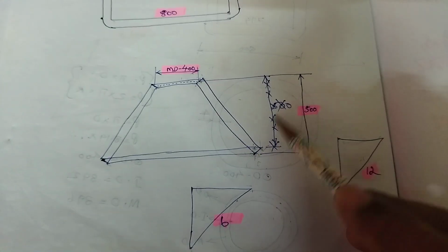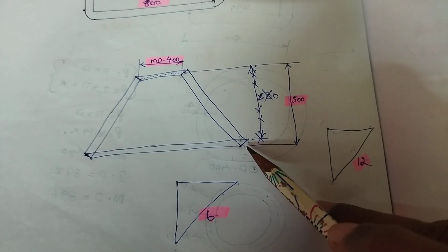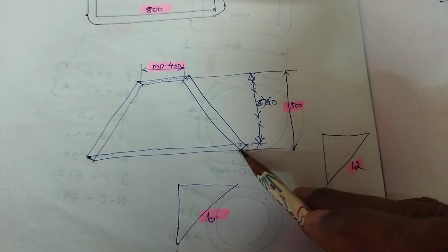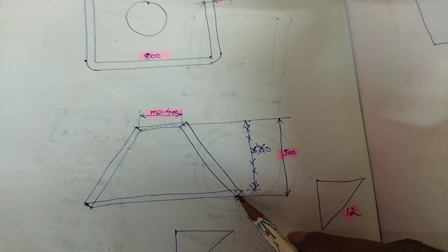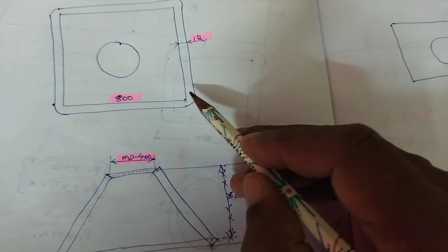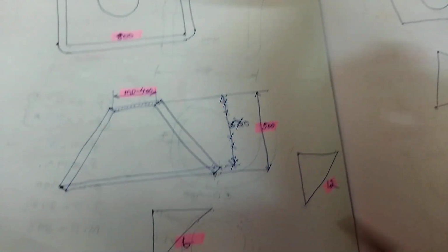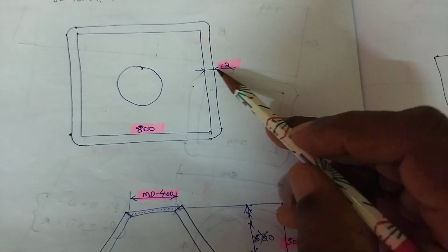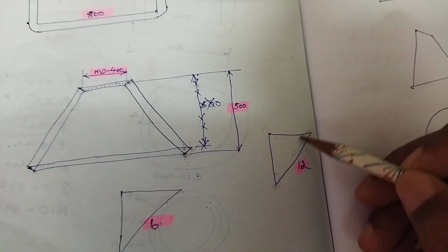But this job has another place in the square area. There, which line will we have to take? This line has to be taken. From this line, bending happens. Inside, there is one line, a corner, where sharpened bending happens. Okay? Remember, what is this much of length? It is the job of 12 mm thickness. So this taper length will be 12 mm.